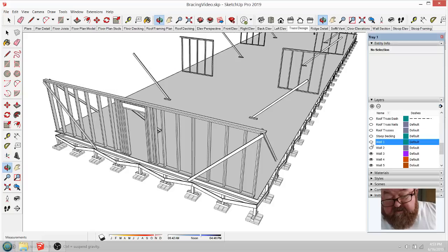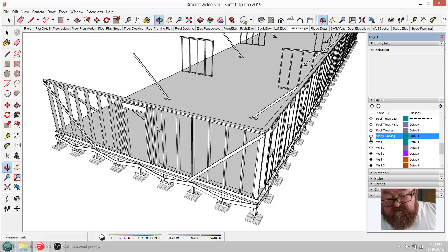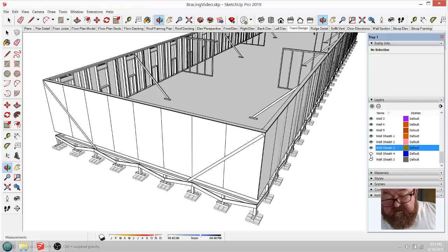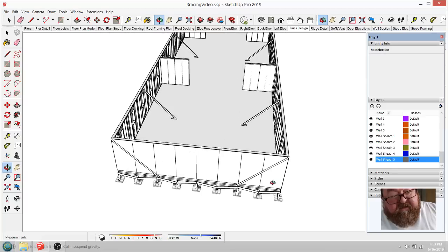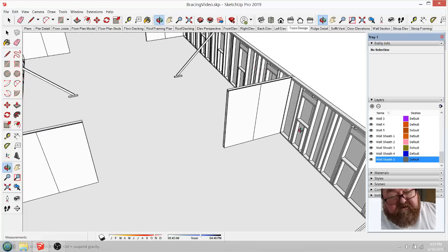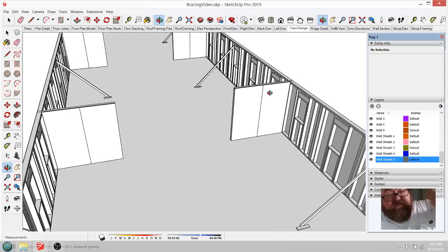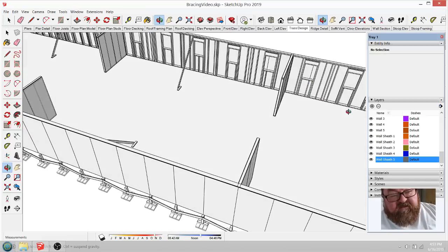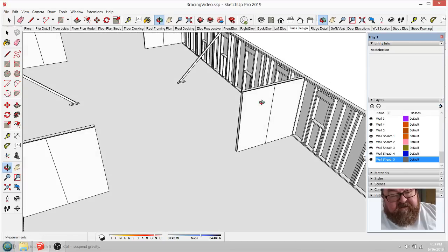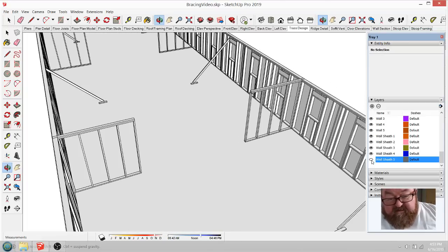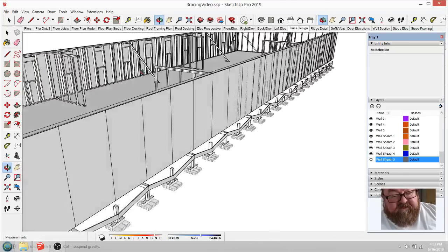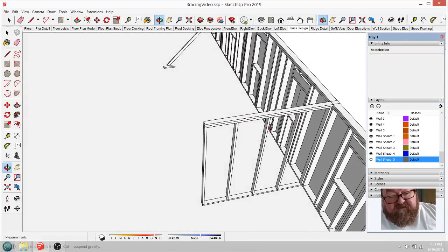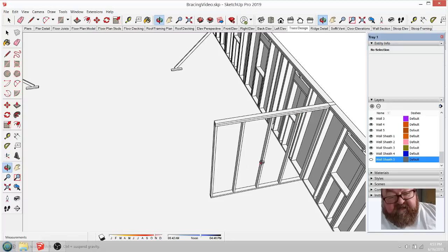Oops, I'm turning on the wrong thing. To my sheeting. So we're going to put all that on, and now here's the thing. The reason it is important to have these temporary wall braces is because even though you're going to frame these, even though you may have this sheeting on, you may be taking advantage of these walls to put electrical in, like you may have an outlet or something.